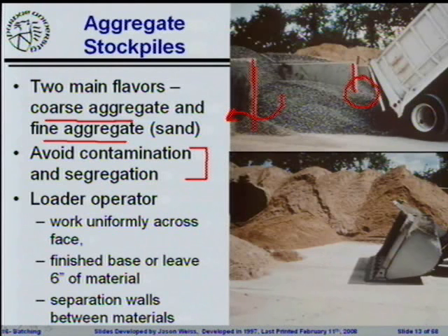All right, one of the other big issues that you're going to have: in both of these facilities, they are on concrete platforms, so you're not going to get the loader operator digging down into the subgrade. But one of the problems that we ran into most frequently was an overzealous loader operator who really wanted that last couple inches of aggregate. And he would try to scoop it up out of the bottom, and all of a sudden he would have a big ball of mud, two soda cans, and something else that was being thrown through the system. So you really want to make sure that you're avoiding contamination not only from the bottom, but also contamination from the other aggregates that are present.